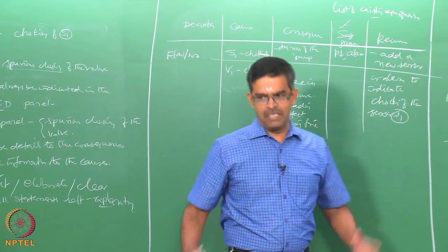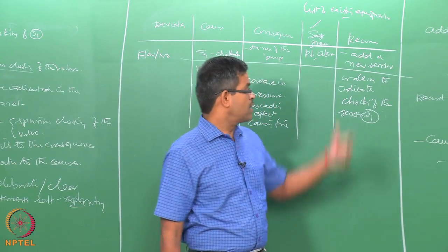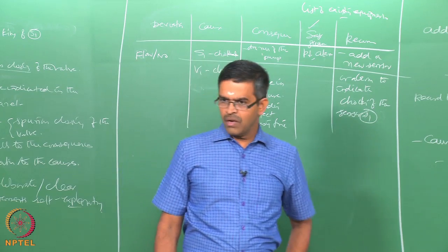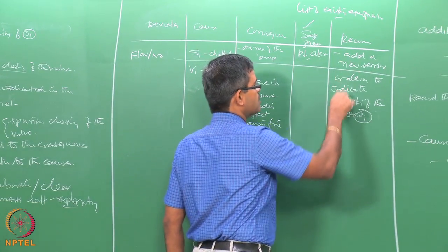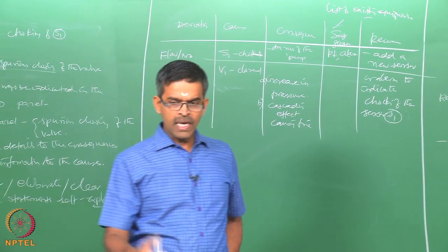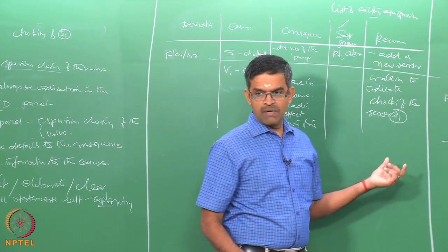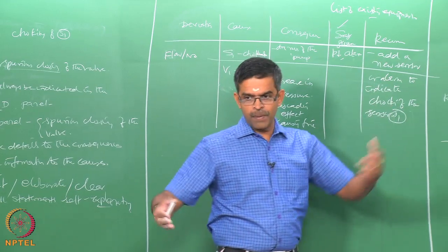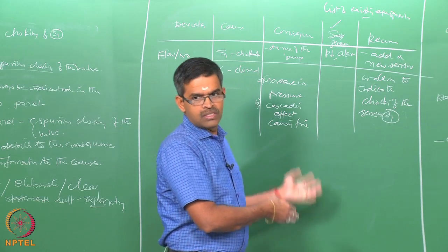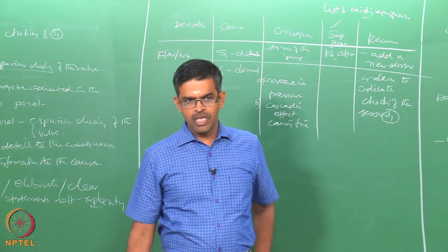So, a report should be complete. You cannot simply leave it to the reader, assuming that recommendations will become a part of the reader's job. Why? Because a Hazop report, as I said, is a legal document. Any recommendation suggested by the Hazop team has to be mandatorily followed by the company, or the company has to give an explanation for not complying with the recommendation given by the Hazop team. So the Hazop report becomes a legal document. Therefore, any legal document which is going to challenge the safety practices of the company should not have any ambiguous statements. It should always be complete.